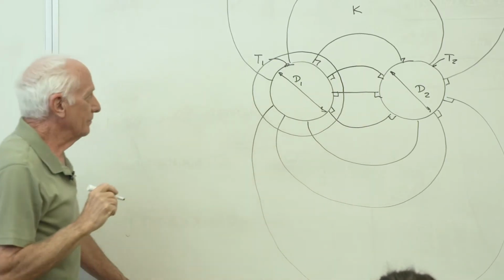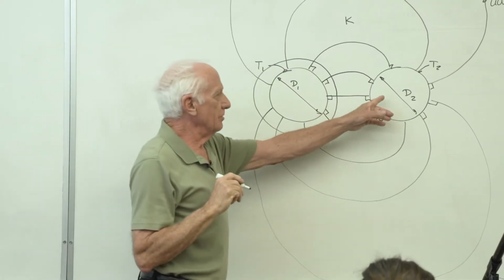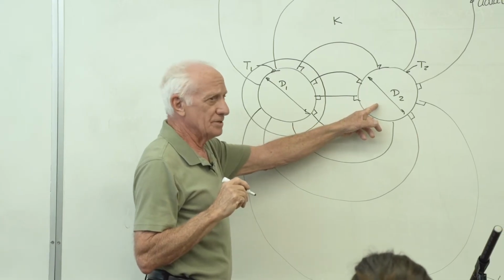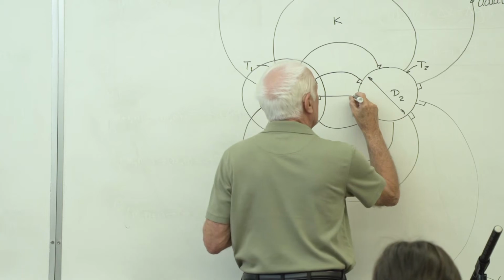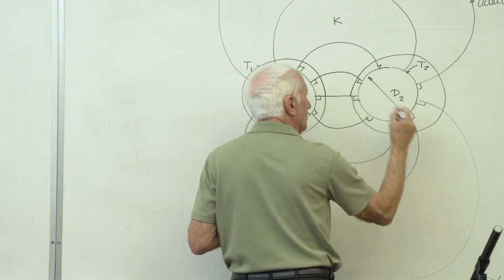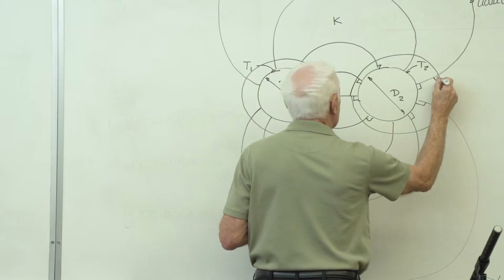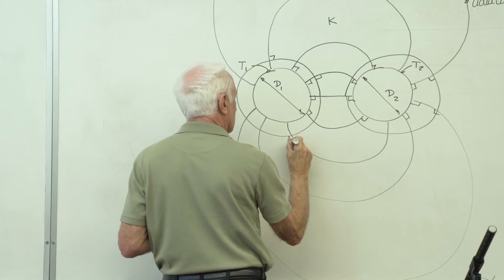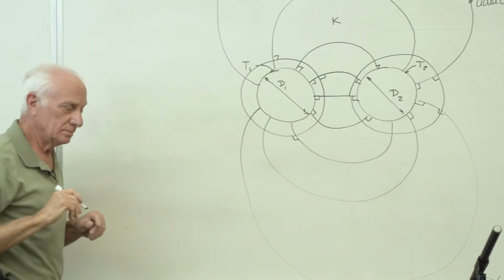Okay, so there is the 90-degree line. T2 is 0 degrees. It's a circle. Where do you think the line 10 degrees is going to be? You know, I think it's going to be really close like this. Yep, you got it. Now here's the rule: everywhere they cross inside, they must cross at a right angle, as best you can draw.